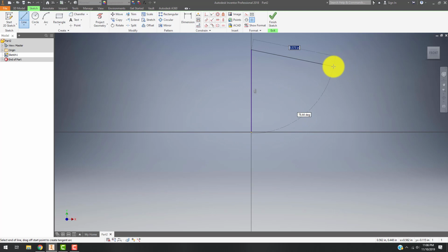Essentially, what we're going to do is we're going to draw a line, and everything that we do is going to revolve around that line. Think of a door hinge. Kind of a door opens and stays. The one edge of it stays against the side of the wall there. That's kind of how Revolve works as well. So we're going to go ahead and have our vertical line, which is going to be our hinge, and then we're going to draw whatever we want to have happen after that.